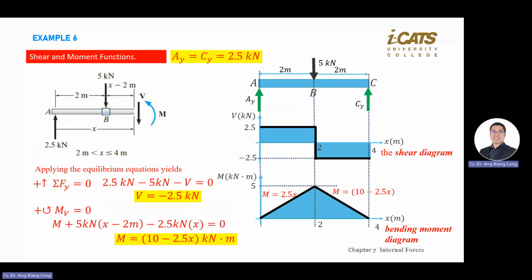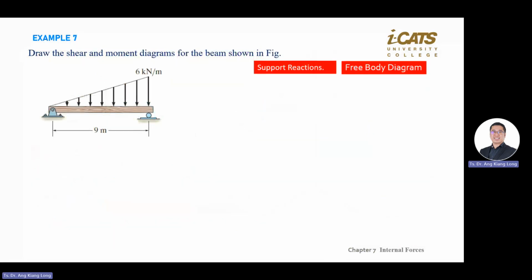Okay, we are done for the focus load. Of course, for static or dynamic, you will see distributed load. We almost done for the section already. I want you to observe what happens if you have a distributed load. You'll get a curve. The steps are still the same. The rest you can view later in my PowerPoint slides. Draw the free body diagram. Find the reaction force.